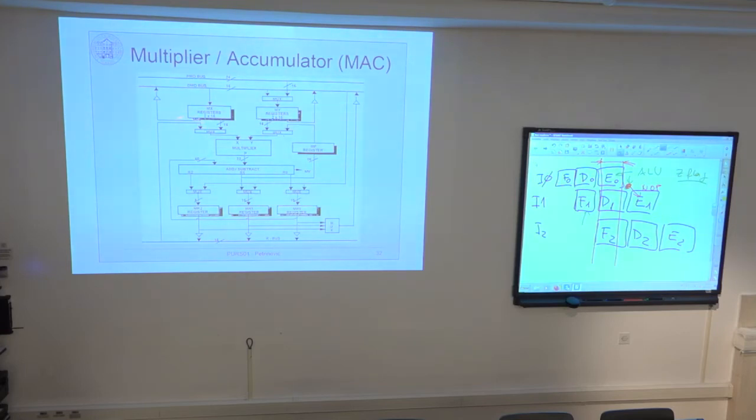The same as with the ALU unit, as a left side argument, I can use the result bus. So for example, AR, the output of the ALU unit, can be used as a 16-bit left side argument for multiplication. And the same as the ALU unit, I also have a feedback register for the right side argument. This feedback register is 16 bits wide, and of course the question is, which 16 bits of the 32-bit product do I use? Because the product of two 16-bit values is 32 bits wide.